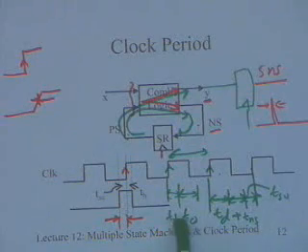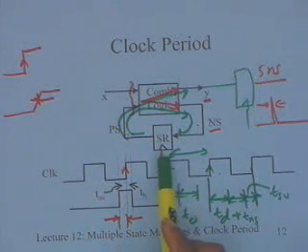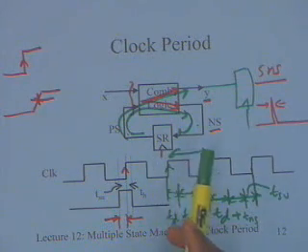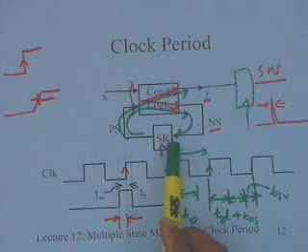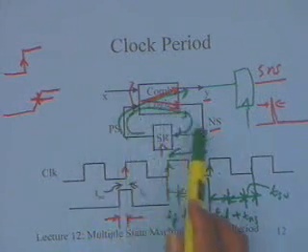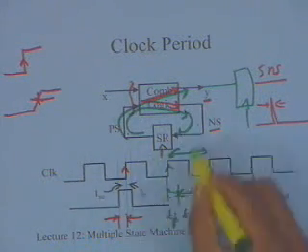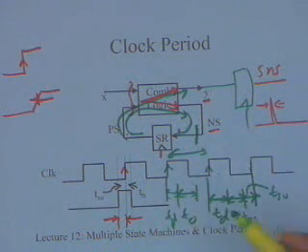So shouldn't TH be added to both those expressions as well? No, TH is not required. TH actually overlaps. TH is more a condition on the input. TH overlaps with TD. Typically TH is much less than TD. So you have to keep the input held, because after all the delays, what you really need is this particular input should be stable longer after the edge has come.